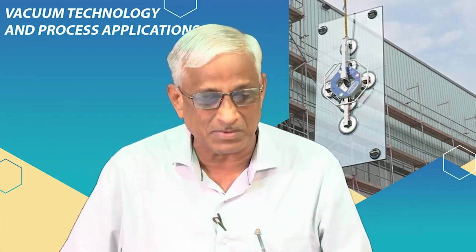Now, we are not that much interested in partial pressure instruments nowadays. In olden days, pressure measurement and partial pressure measurement were all very important concepts. Right now, if there is a trouble, vacuum is not coming, leaks are there or outgassing is there, how do we know? RGA shows outgassing, the leak detector shows leaks immediately. Solve it, then go to the process, adjust the process parameters and use the RGA to know the chemistry under